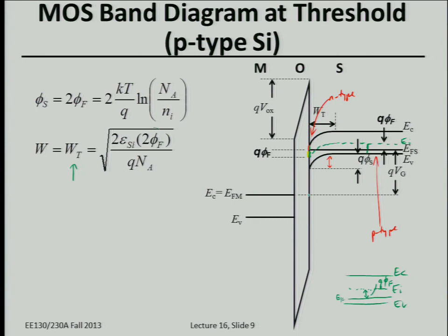Then, in principle, you're already starting to form an inversion layer of electrons. But the concentration of electrons is still negligible compared to the concentration of ionized dopants, so we consider that to be negligible. We only consider the mobile electron concentration at the surface to be significant once it reaches the ionized dopant concentration level and beyond. And was your question about the thickness of the inversion layer?